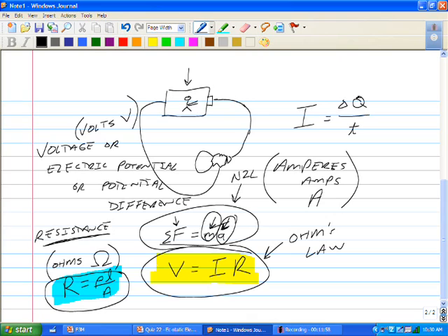That means I have a fire hazard. Instead of putting two 100s together, it is a fire risk depending on the current flow through it. It's possible. I mean, it depends on a lot of other things too, but there is a risk.